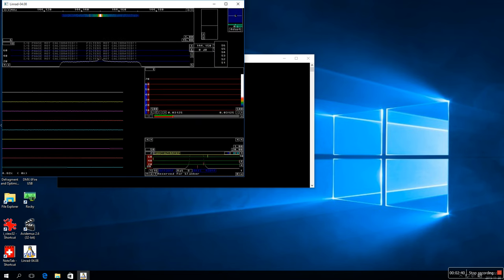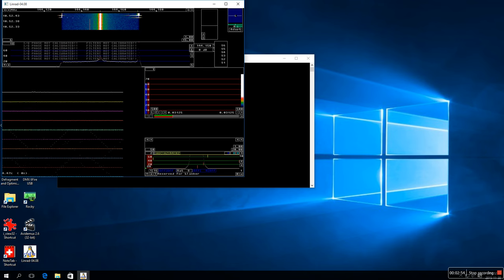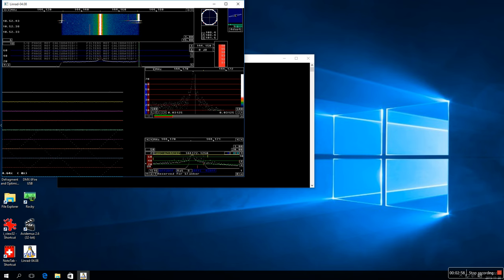Oops, does not look so nice, does it? I move the frequency down until it comes within the passband here, and look at the polarization we have here. It has left circular, and the angle comes out at 43 degrees or something.